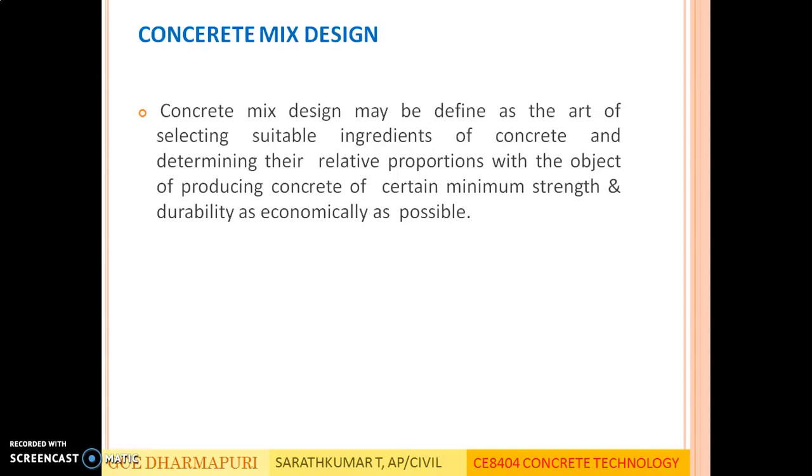So in mix design, first you have to choose the materials, and once you have selected the materials, you have to know the properties of the materials, namely cement, fine aggregate, coarse aggregate, admixtures, and water. And once you choose the material, you have to proportion it such that when the concrete is done, it should have the desirable quality. So this art of choosing the materials and knowing what proportion of each constituent material to be used is mix design.